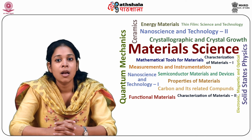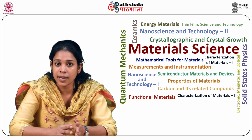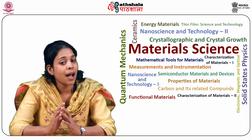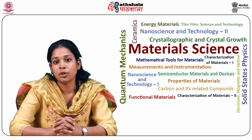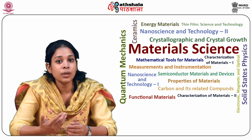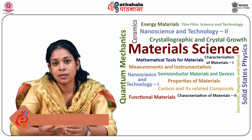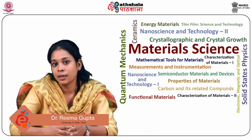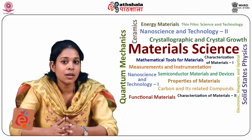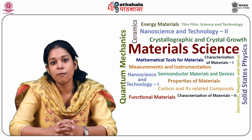Moreover, we have learned that the stabilization with yttrium oxide or cerium oxide can be utilized to produce a material called tetragonal zirconia polycrystal, which consists of grains of tetragonal phase, and in this the grain size is very less than 1 micrometer, and the material has high strength and high toughness due to the transformation toughening. Similarly, as in the case of alumina, we have read in zirconia also how the structure is changing from one to another with changing various parameters, like in the case of tetragonal zirconium oxide particle in a matrix, the toughening is due to the stress induced when the tetragonal is transformed to monoclinic in the stress field and results in large enhancement of fracture toughness.